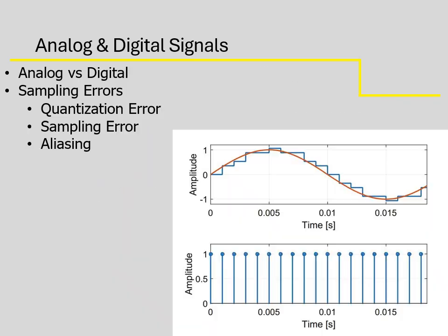Okay, let's move on. All right, so let's talk about some problems with digitizing analog information. So here's an example: the red is the analog signal, and we are going to convert it to digital, but we can only take samples every so often, at a certain frequency or rate. So this right here is your delta t, or your time step. Okay, that's when you're sampling. So only at those times are you recording a sample.